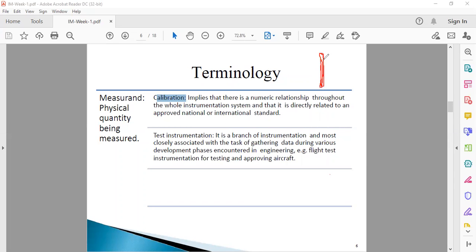So, as long as it is not calibrated. Once it is calibrated with the standard, there are a lot of methods for calibrating any instrument. For example, I place this thermometer on a known hot plate. This is a hot plate, and the value of the temperature at any instant can be found by this knob. If I rotate the knob to 5 degrees C and place this thermometer there, the mercury will rise to some level.